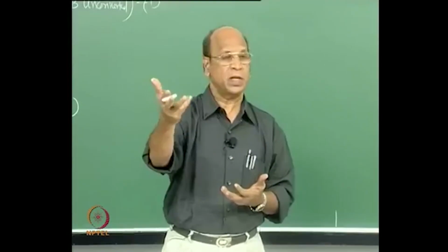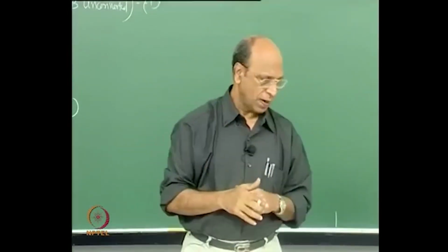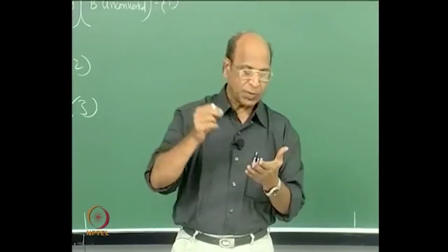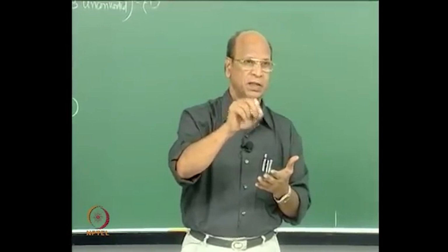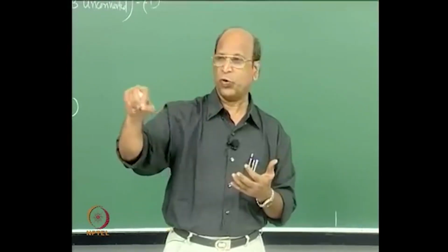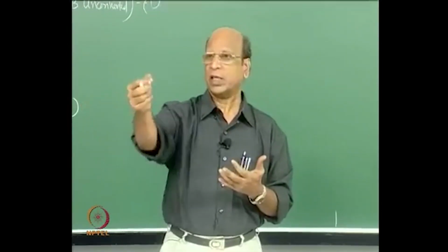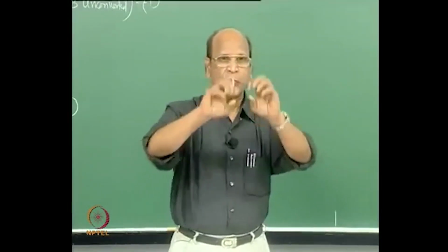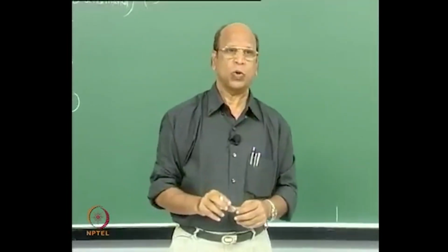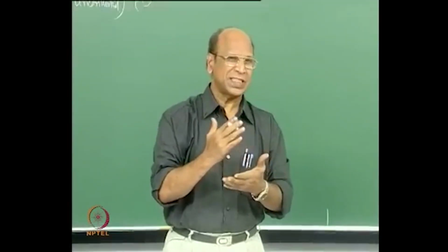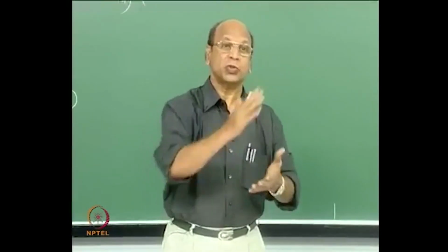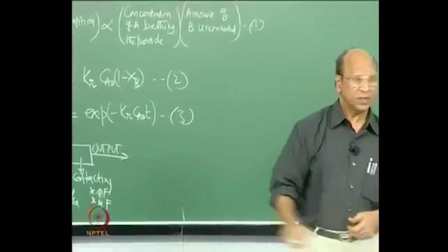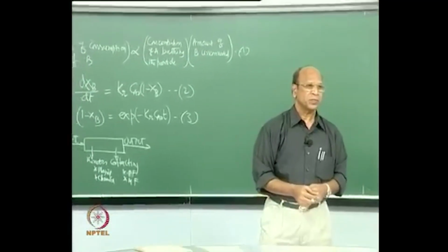Like for example, I have been telling you the example of FCC. FCC catalyst is a highly porous particle, but one of the side products of fluid catalytic cracking is very fine carbon, coke. That coke will go and sit uniformly here and there throughout. Then the surface area which is actually participating in the reaction is slowly decreasing. That decays exponentially if I assume first order kinetics there. In fact, the same equation can also be used.